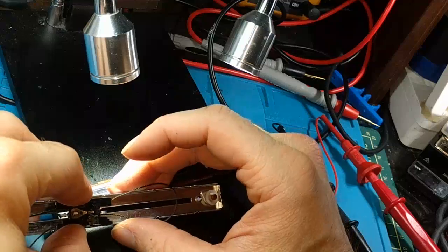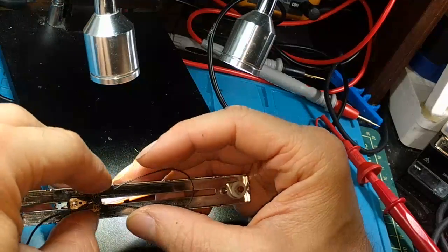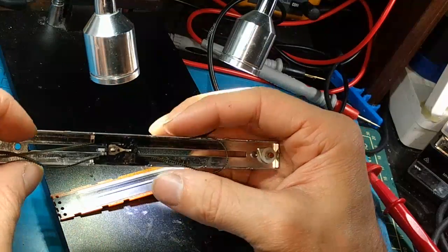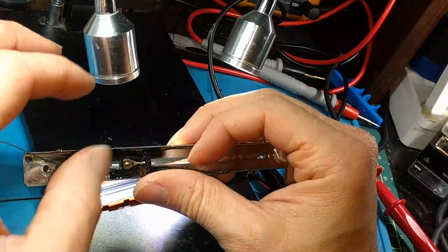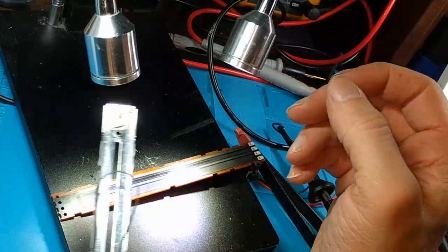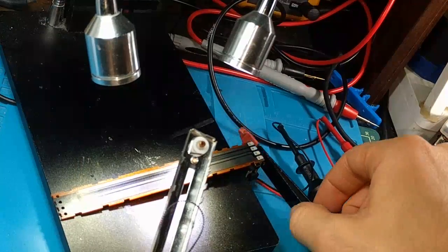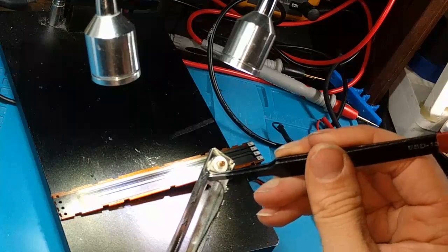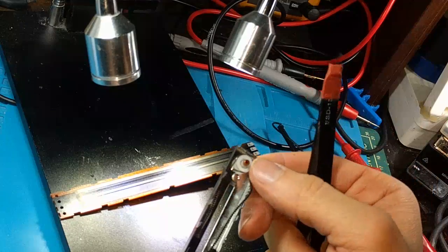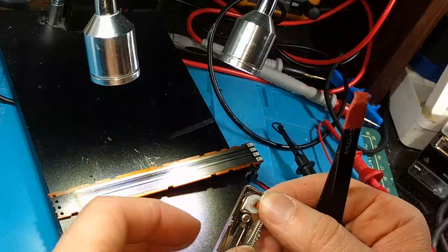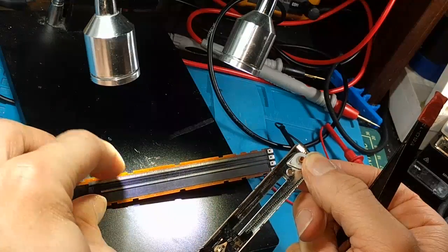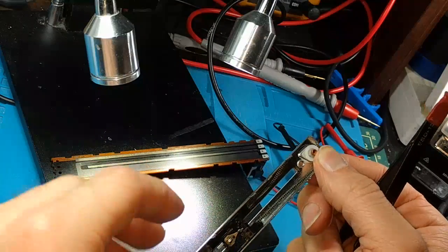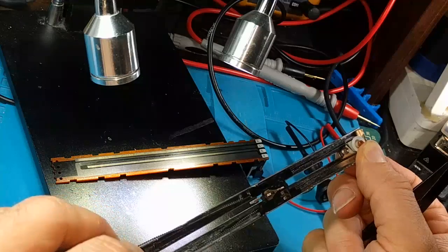There's a notch where the teeth actually lock into the black plastic, and then there's a slot that's just kind of open-ended, and that's the part that actually pulls. And so you've got this pulley at the end here that you wrap around like so. There is an orientation to this, so make sure that your two teeth match the two tracks here on the top, and not the other way around, of course.